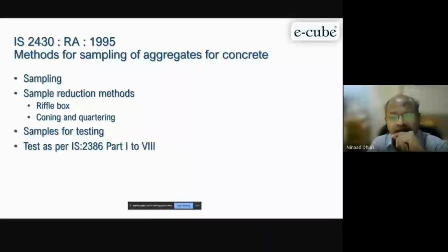Secondly, include even fine aggregate also. Suppose there are 5 mm, 6 mm particle sizes, and some particles of around 150 micron, 75 micron, which is very, very fine. When you unload on the stockpiles, you'll find that the fine and coarse aggregates are separated. So when you are batching, you are supposed to mix this with mechanical means. We have a loader or JCB bucket. You mix it and then we can go for production. Similarly for sampling also, we need to have proper sampling.